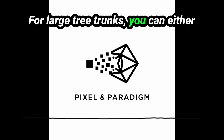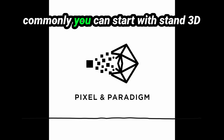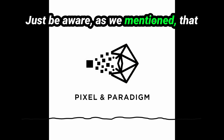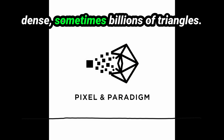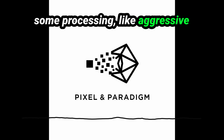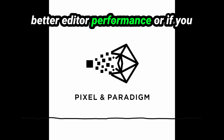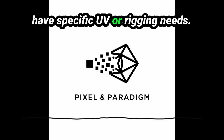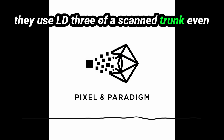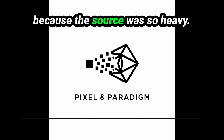For large tree trunks, you can either sculpt them from scratch, which gives you full control, or increasingly commonly, you can start with scanned 3D assets from libraries like Megascans. Just be aware, as we mentioned, that raw scans are often exceptionally dense, sometimes billions of triangles. Even with Nanite, they might need some processing like aggressive decimation or maybe even retopology before importing, just for better editor performance or if you have specific UV or rigging needs. I remember reading one artist mentioning they use LOD3 of a scanned trunk even before enabling Nanite just to make working with it in the editor smoother because the source was so heavy.